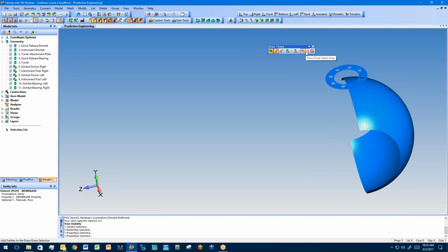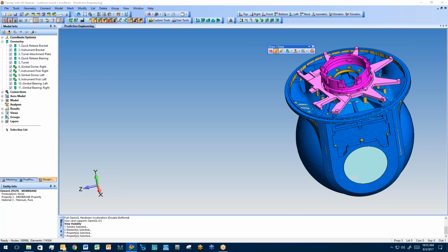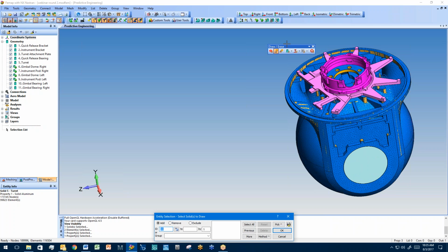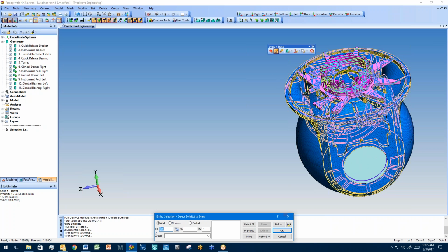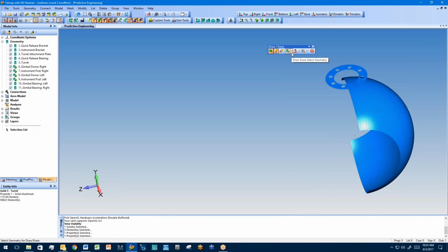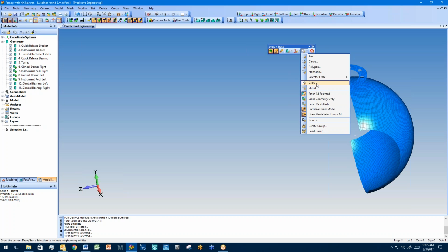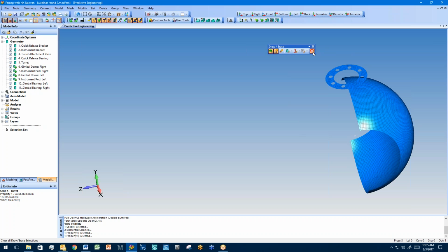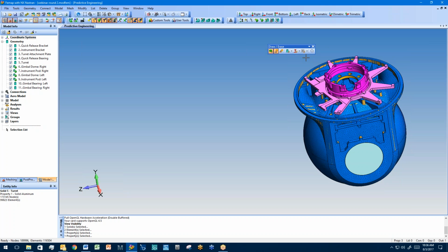It's just really handy. Hey, when you pick on a solid, make sure you mention that what's unique is when you pick via solid, it includes the auto select mesh. Exactly. That's what I was talking about earlier. When I first saw the auto select mesh, I went, "Wow, that's super handy." And this grow and shrink button is probably my favorite. They had it as an API for a long time, the grow shrink, but it meant you had to create a group and then grow and shrink. This is so much faster, but I have to learn how to use it. Yeah, it's super handy. I've been enjoying it for sure.